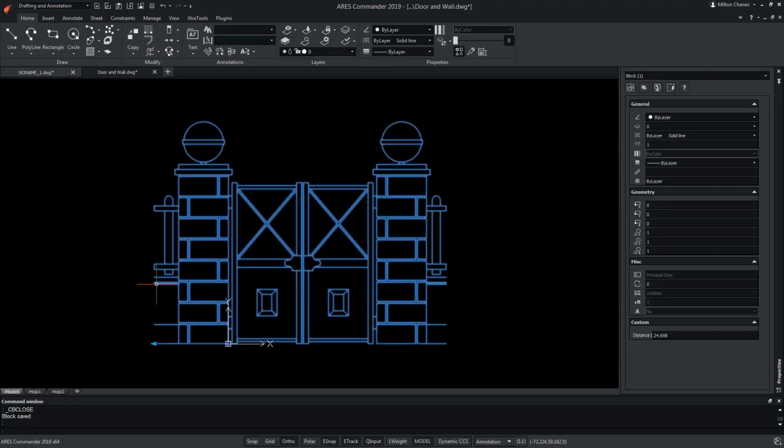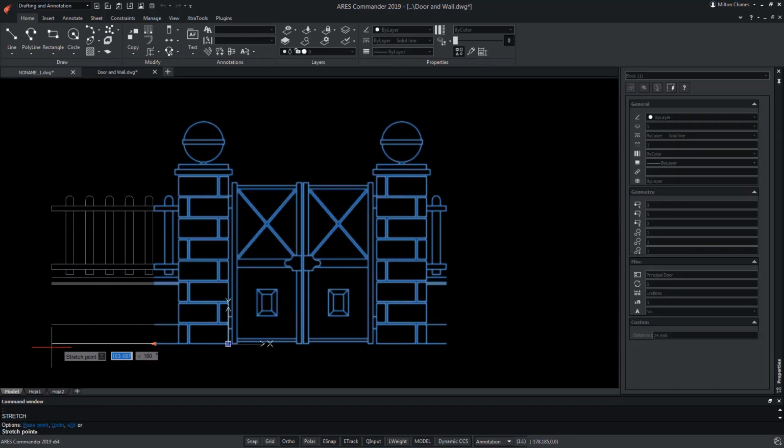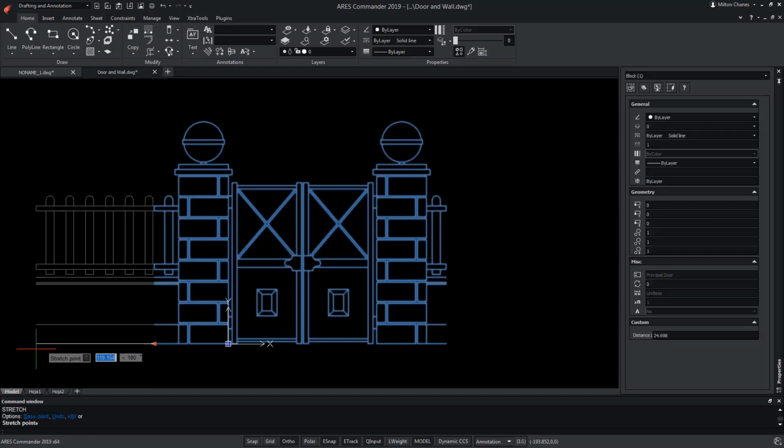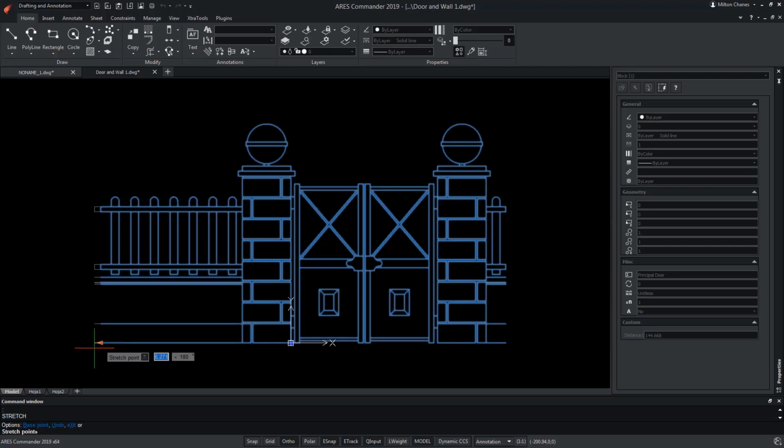Now, after selecting the block, we stretch the grip. As you can see now, the operation is complete, and as the wall is stretched, the vertical part of the fence is also copied. Pay attention to the following. When moving the grip, the horizontal elements are created until at some point a multiple of the distance indicated in the pattern appears, a moment in which another vertical frame of the fence appears.